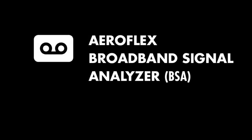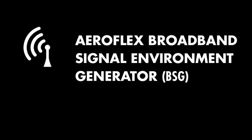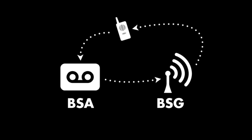The Aeroflex Broadband Signal Analyzer and Recorder allows you to monitor, record, and perform detailed analysis of RF signals and environments. The channel power and environment signal parameterization tools are just a few of the available analysis functions that BSA has. The Aeroflex Broadband Signal Environment Generator allows you to replay back into the environment recorded and synthetic signals with the ability to modify them on the fly in order to stress your network. In this demonstration, we have recorded a live radio transmission with the BSA and played it back over the air to the handheld radio using the BSG.